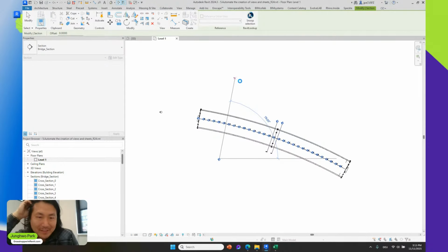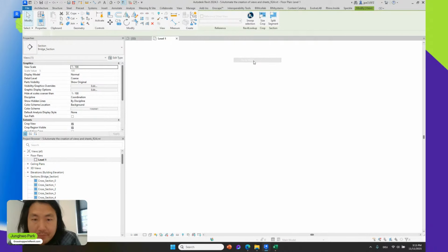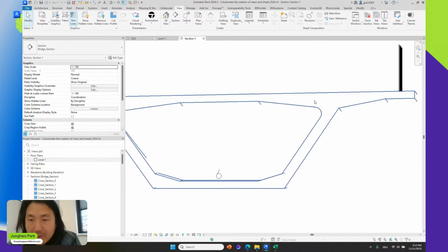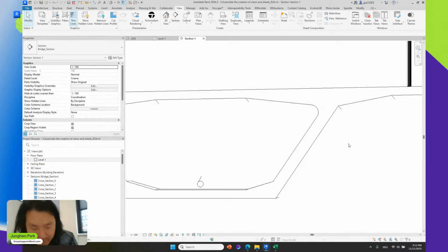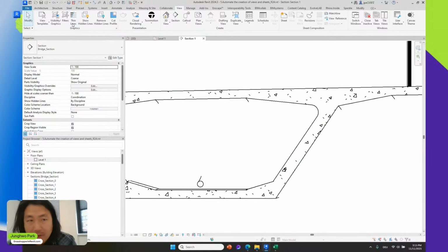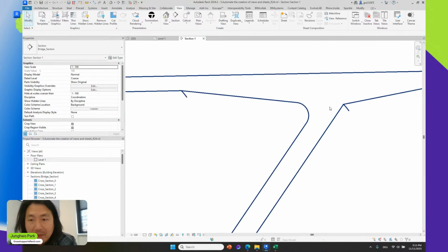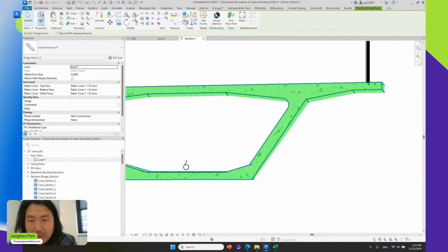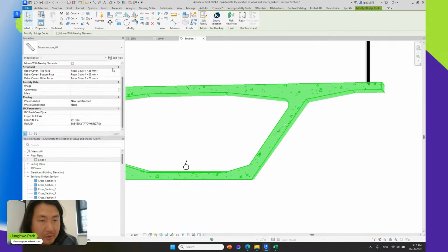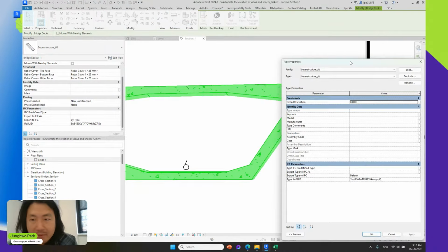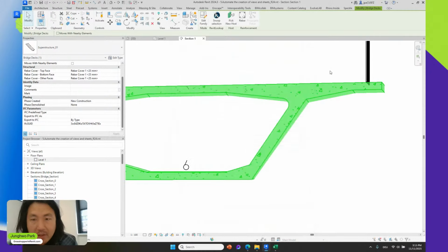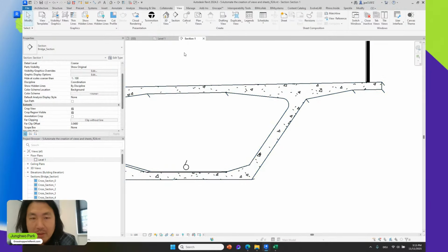So it's just a section drawing. I go to the view, and you can see this, because it's not a direct shape anymore, you can actually get the correct line weight according to your object styles in Revit, and the hatches and all kinds of behavior. But the beauty of it is that you have the correct category, and you can fill in parameters, instance and type parameters accordingly, and then you can document in